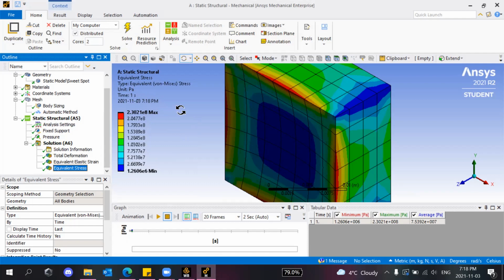I'm not exactly sure, but you would just compare with your yield strength in your engineering data, and proceed from there to make sure, okay, as you can see, my corners have reached past the yield strength of my door, and therefore this piece will break off. So that's how you would get results from a static structural simulation. And I'll be going more into the questioning of your results in the example later in this workshop.